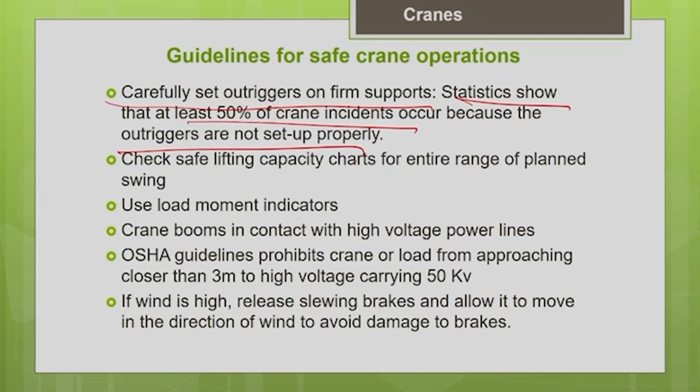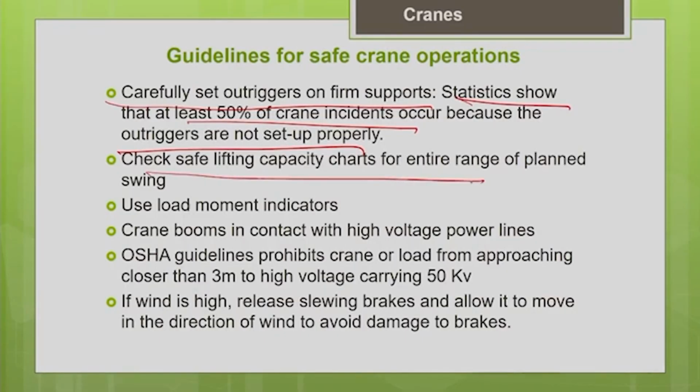That is why we have to carefully set the outriggers, and also you should check the soil condition. If the soil is weak, provide some timber mats or steel mats, and place the outriggers on them. Check the safe lifting capacity charts for the entire range of planned swing.